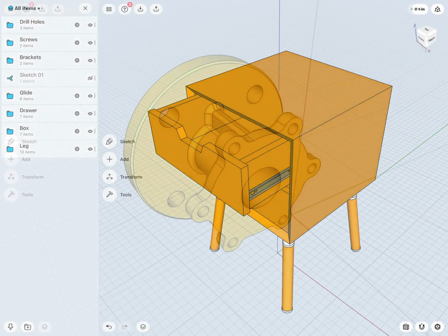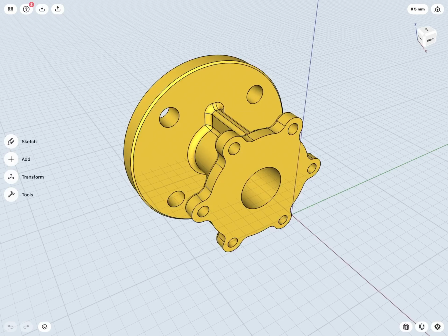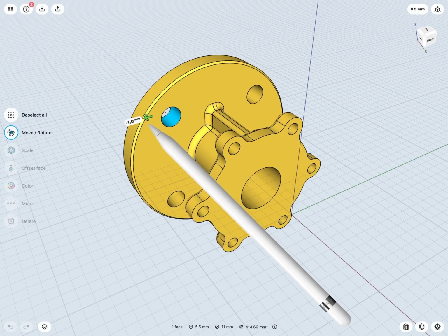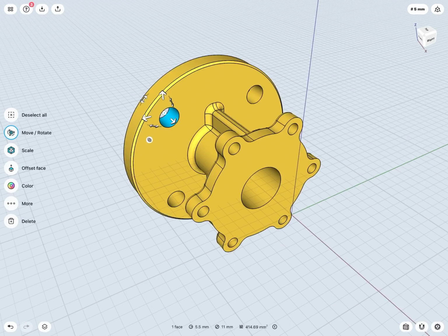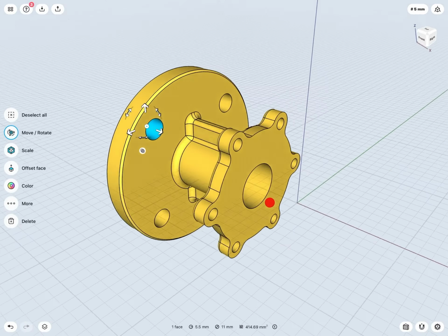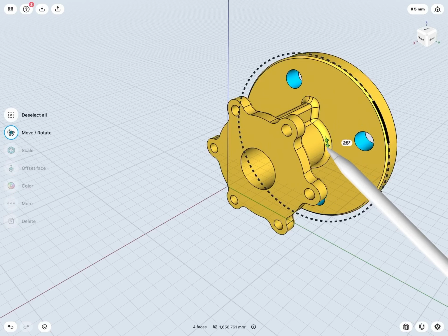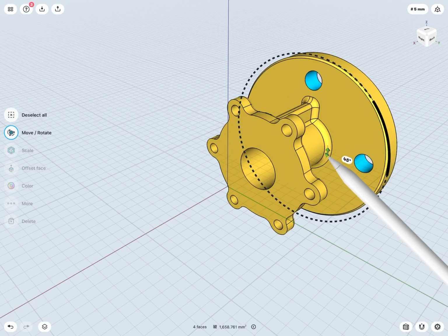What's also very handy with the move rotate tool is I can move or rotate existing features as well. So for example, a hole, I can tap to select a hole, and I can move or rotate that particular hole as well. So for example, let's say I wanted to change the angle or rotation of all four of these holes here. I could simply make sure that my pivot point, again, is centered along this circular edge here. So again, just move your pivot point, and as you hit any entity, it should try to jump to those specific entities. So if I go over a circular edge, it should jump to the center point of that circular edge. And now I should be able to rotate these holes to change the angle. Maybe we'd like it something like this here.